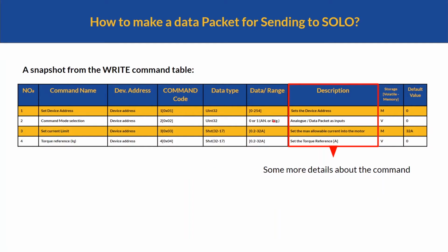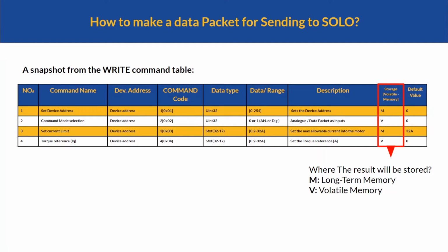The next part is the description of these commands a little bit more, and the next part, which is a little bit important, is telling you where the results will be stored. So if you send a command like to set the device address of Solo or select the command mode type, where will the final result be stored? So we have two different storage. We have the long-term memory, which will not be affected by power recycling or turning on or turning off of Solo.